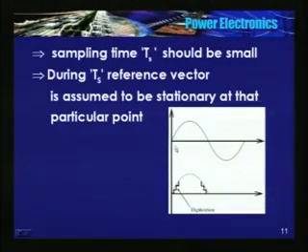See, here is a pure sinusoid. That's what we want. Call it VAN. If we use 180 degree conduction, VAN has 6 steps per cycle. There are 6 steps, each of 60 degrees. Height is 1/3 VDC, 2/3 VDC, again 1/3 VDC. Now, of course, it is rather impossible to get a pure sinusoid.